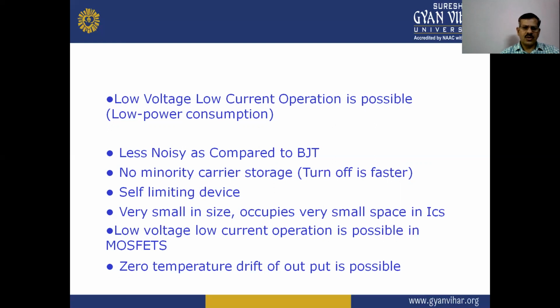In FET, no minority carrier storage, so turn off is faster, and FET is a self-limiting device. And also FET is small in size, occupying very small space in integrated circuits.